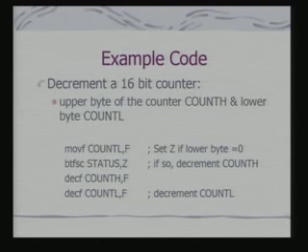So obviously, if I have to implement a 16-bit counter, what do I need to do? I need to use 2 memory locations and not 1, because effectively each memory location is of length 8 bits. Okay? In this case, I am using 2 locations.